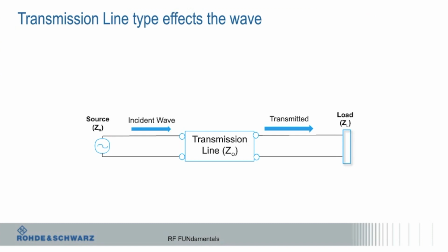Okay, so let's see. Transmission line waveguide. So these are some of the waveguide bands, and I would find it unlikely most people here would probably ever deal with these. But these are some of the different types of waveguides. This is the bandwidth. So, waveguides act like a bandpass filter. When you get outside the bandwidth of that waveguide, it pretty much doesn't pass anything. And there's the band names. More often than not, these are used by satellite people. They like those band nomenclatures, and they do high power too.